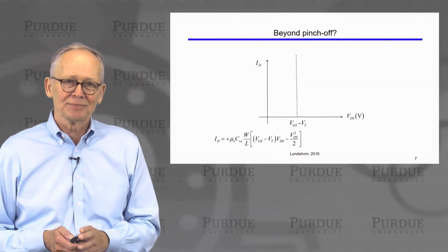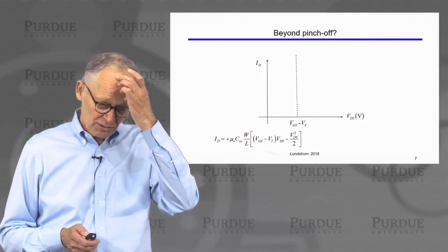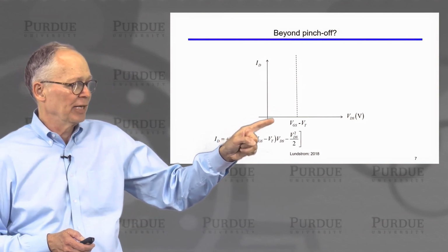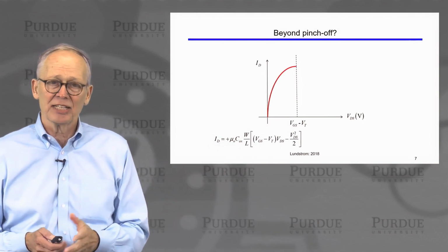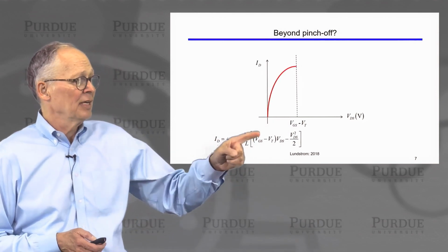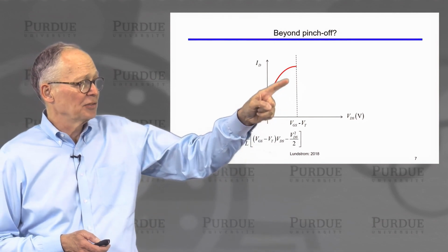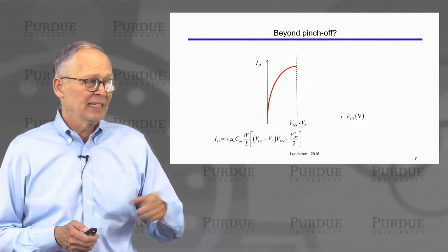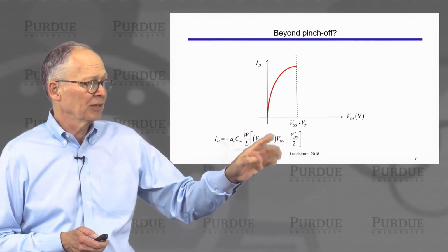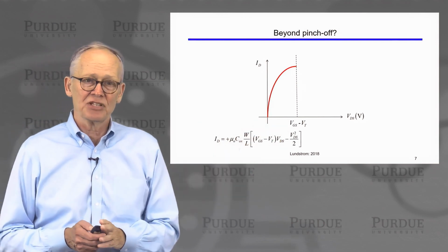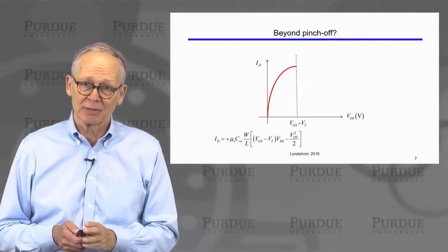All right, let's plot this characteristic that we just derived. If we sweep VGS, if we sweep the drain voltage up to VGS minus VT, we'll get a curve that looks like this. And you can convince yourself that once the drain voltage hits VGS minus VT, the slope of this curve becomes 0. As the drain voltage gets bigger and bigger, the current rolls off, and at this critical voltage, VG minus VT, we reach a maximum.